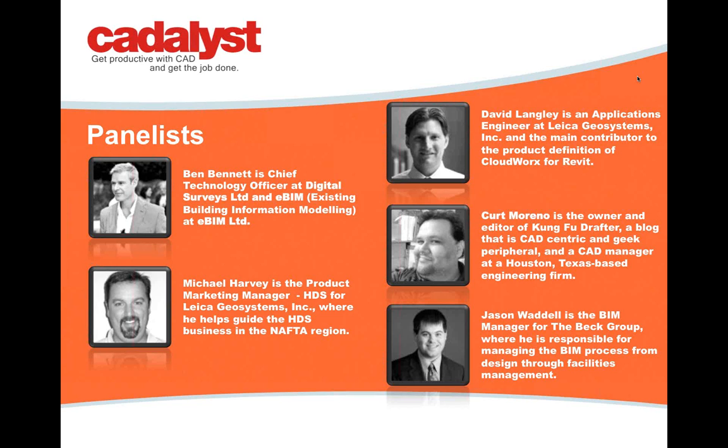Sure. So how it happens is you go out into the field, collect the data from the laser scanner, bring it into Cyclone, which is our main product, and that's the database that has the point cloud engine and everything in it. So once you have all of the data in database form in Cyclone, you can go ahead and install CloudWorks on top of Revit or AutoCAD or MicroStation or what have you, and then you can browse to that database that is in Cyclone and open that up. It uses the rendering engines in those platforms, but still is running our Cyclone main engine that has an unlimited amount of points that you're able to load into it and view.